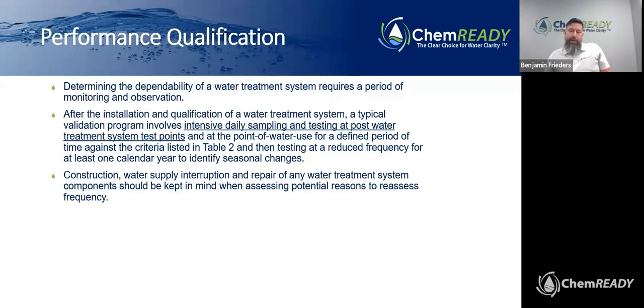I'm going to do it twice a week. If those twice a week samples all come back negative and within range, I'm going to bump that to monthly. So all to say, it depends on your facility and your water quality specifically. And if you can show a logical path and logical data on the decisions you've made, which we as consultants can help you develop, you're going to pass the audit and you're going to pass the inspection.